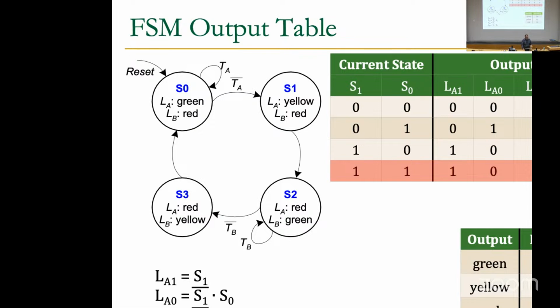Yeah, exactly. We're going to have a slide about encoding, and encoding actually affects the simplicity of your design. There is a trade-off between the number of flip-flops that you are using and the simplification of the equation, so it's the designer's job to decide which encoding is the best. For this one, here is just an example. We are considering this encoding without any discussion, but we're going to see the trade-off later. That's a great question.